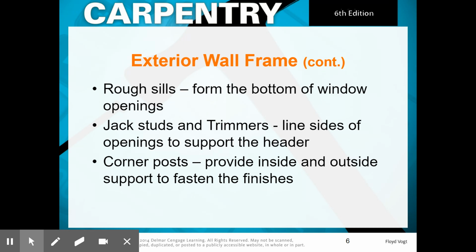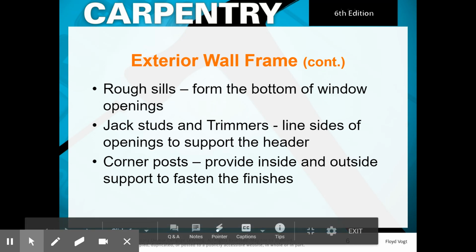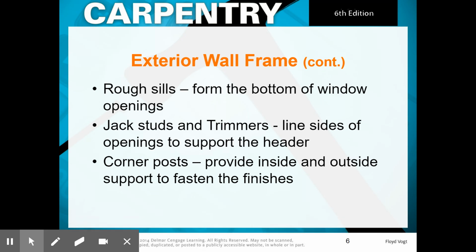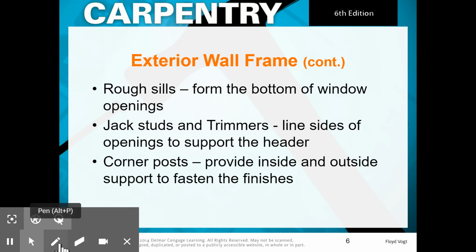Corner posts provide inside and outside support to fasten the finishes. Now, one thing we'll go over with the corners is that we need to be able to attach finished material, let's say plywood, to the outside corner, but they also need to be constructed in a way that we're able to easily attach finished materials such as drywall to the inside.